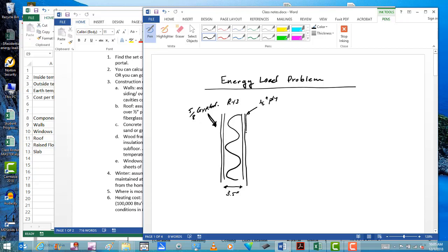And you've got a thin little layer of tar paper, which serves as a moisture barrier. So we'll call it tar paper, for lack of a better term. And then you have some kind of siding. Might be bricks, might be stucco. In this case, it's a tapered wood siding. Each one of these has an R value associated with it that comes from that table we just looked at. The 5/8 gyp board is given in the table at 0.56. So let's add them up here. 0.56, this R value is given. The insulation is R13. 1/2 inch plywood, well, it's 1.25 per inch, so we might have 0.63 for 1/2 inch.